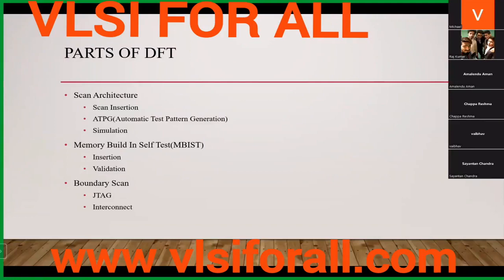So we convert all the flops into scannable flops, and then we generate the chains of those scannable flops, and we insert new hardware for the compressor, decompressor, and there are multiple things during the scan insertion. So we should have multiple classes to understand the scan part of it. When we do the scan, we need to cover the stuck-at and transition faults we have already discussed, and then we generate the pattern through ATPG. We call this process ATPG.